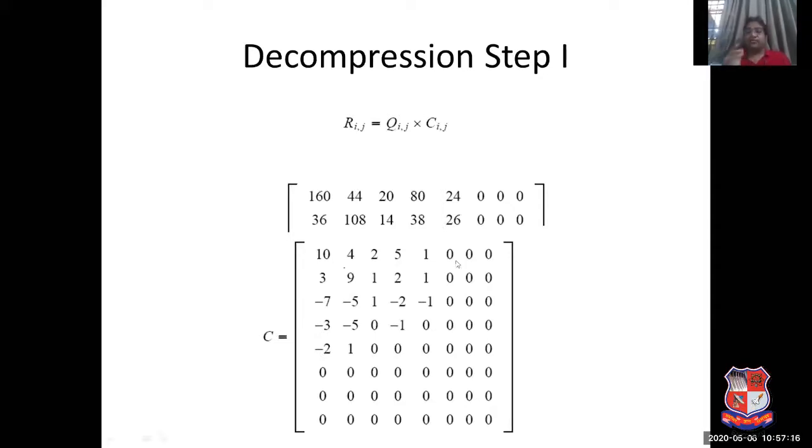As I told you, this is a lossy compression. So most of the values, even after the reconstruction, are 0. And why is it so? Because this is quantization, and once it is quantized, you cannot reconstruct the original values. In each block, originally there were 64 DCT coefficients. Now most of the high frequency DCT coefficients are 0, even in the reconstruction.